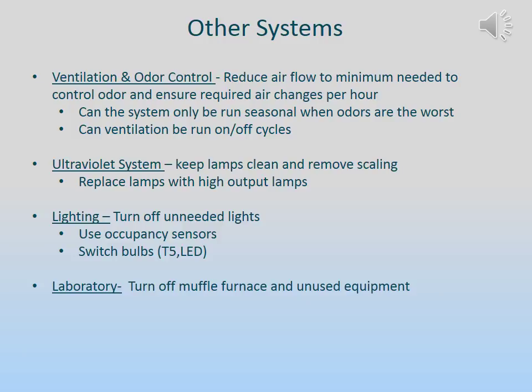With ultraviolet disinfection systems, keep the lamps clean, remove scaling buildup from the tubes, and replace lamps with high output lamps. For lighting systems, remember to turn off unneeded lights. Use occupancy sensors, and switch bulbs to the T5 or LED type. For the laboratory equipment, do we have a muffle furnace we are leaving on all day long when we may only be using it for a test once or twice a week?